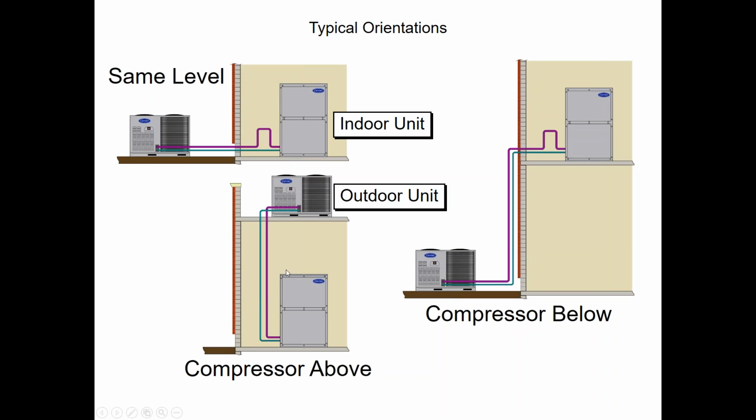With the condensing unit above the evaporator, there's no need for any traps at all. Many years ago in refrigeration, we used to have what were called lift station traps. Calling the line right here a suction, it used to go up about 10 feet, there was a trap, you go up 10 more feet, and there was a trap. As the oil traveled up, it'd fill into the trap. Once the trap filled up with oil, it would blow up to the next trap, and it was just a lift station trap system that allowed us to get the oil back up to the compressor.